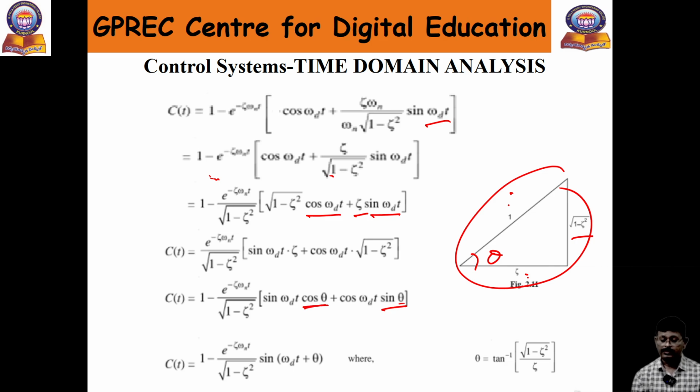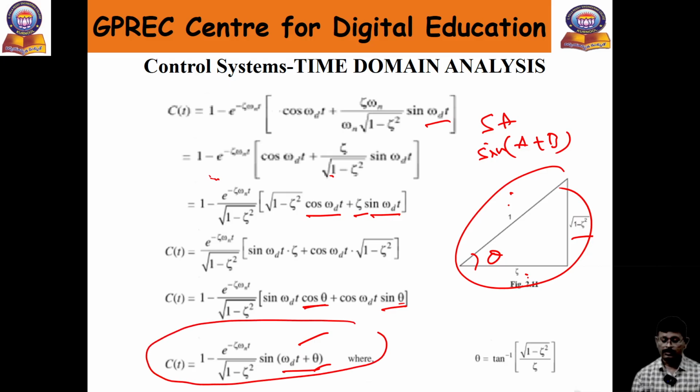Now you will get sin A cos B. In trigonometry, sin of A plus B equals sin A cos B plus cos A sin B. So I am applying these trigonometrical simplifications here. Simply you will get 1 minus e power minus zeta omega t over root of 1 minus zeta square, sin of omega d t plus theta. So this is the second order response when a step input is applied to the system.